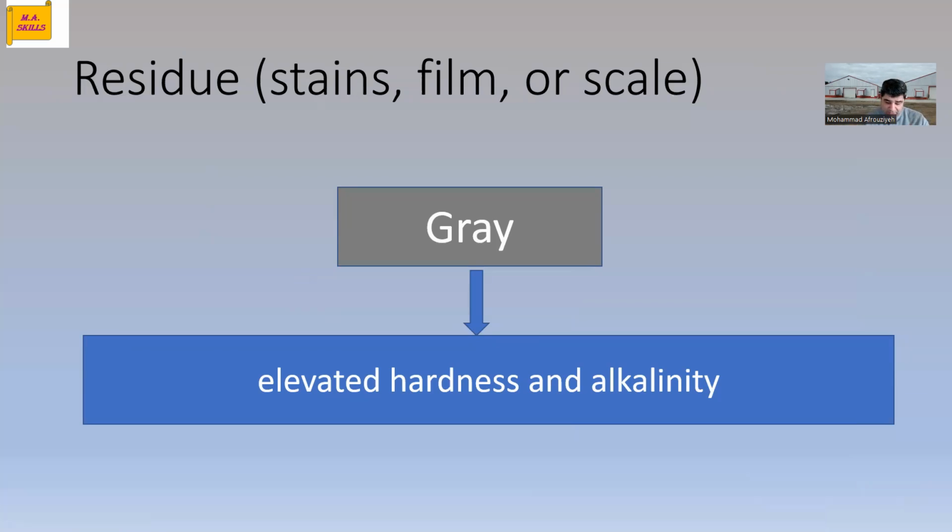And if your water sodium level is high, then you shouldn't use ion exchange unless, instead of sodium chloride in your ion exchange system, potassium chloride is being used. Then, yeah, you can use ion exchange with potassium chloride inside when your water sodium level is high.